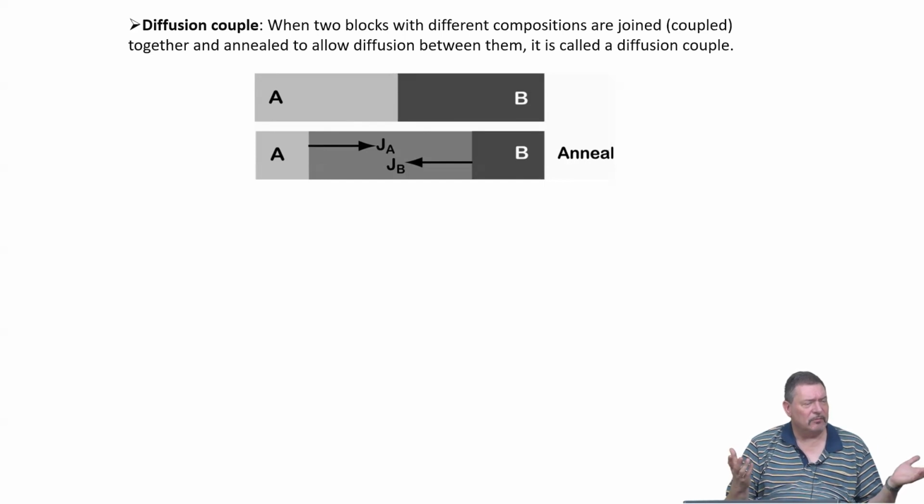So let's say after 10 hours annealing at 500 Kelvin, you don't get a result with your scanning electron microscope. What could you do? Raise the temperature, very good. So you go up in temperature, diffusion gets faster, so you do the same time, but higher temperature. And then at some temperature, you are bound to see something, right?